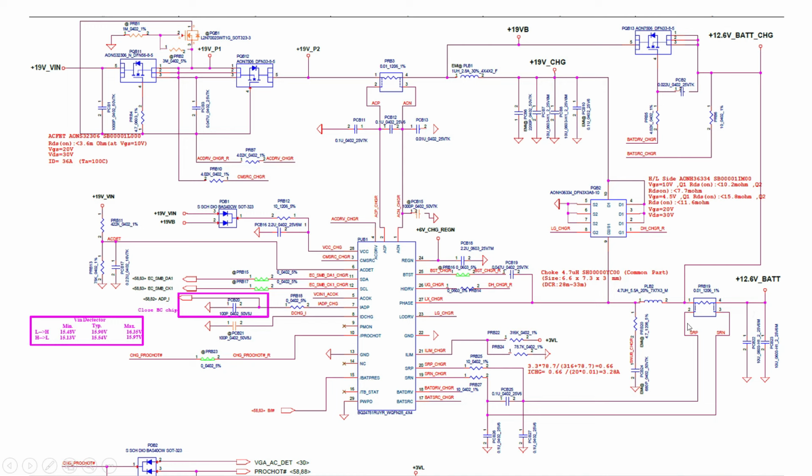Once the DC jack current enters here, it will come to the first MOSFET as well as the input of the charging IC. So now this charging IC will activate because of this 19V in. Once you get the battery connection, the battery voltage also comes here as 19 VB, and that is also connected to the supply of this charging IC, through PQB1. So here there will be two kinds of input, both or any one input, and that input goes to the charging IC.